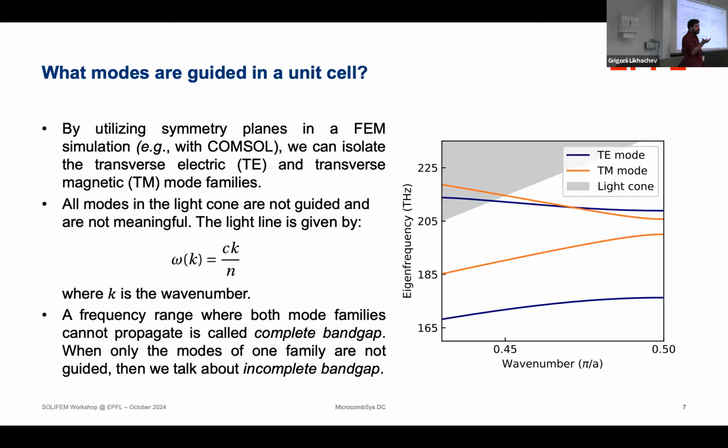Of course, depending on the thickness of your waveguide, if the waveguide is very thin, the TM modes cannot really propagate properly, or at least they will be very lossy. Because it's thin, it's better for the TE. So depending on what resonator you are dealing with, this problem might not affect you.